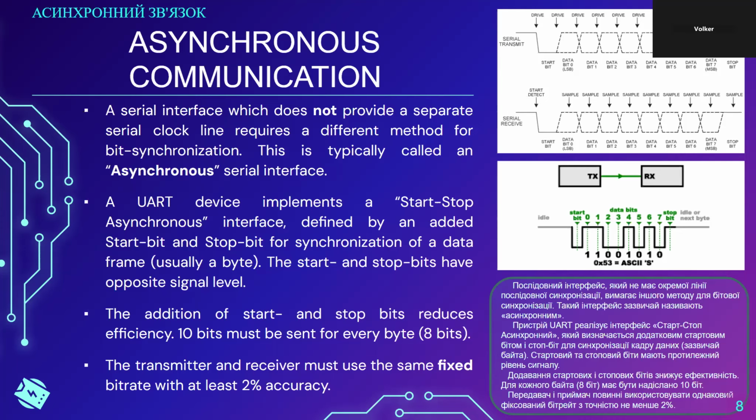Sometimes an RC oscillator that is advertised as 1% accuracy is not actually 1% accurate. If one looks at the temperature extremes, it might just be 3% accurate, so it cannot be used for asynchronous communication. And in that case, a crystal oscillator is required again.